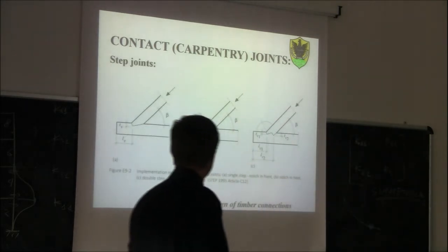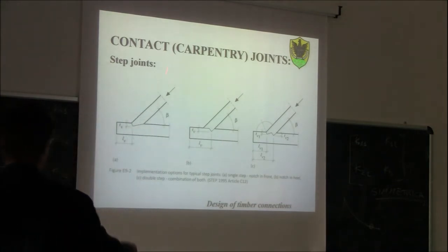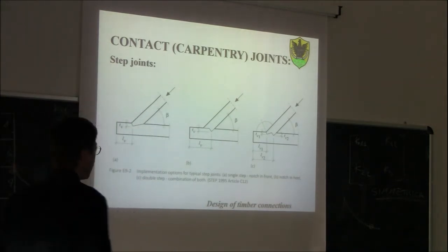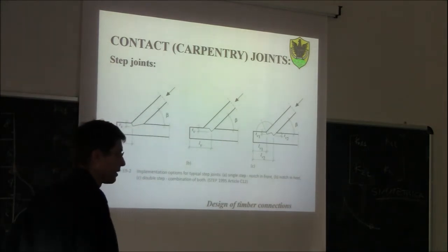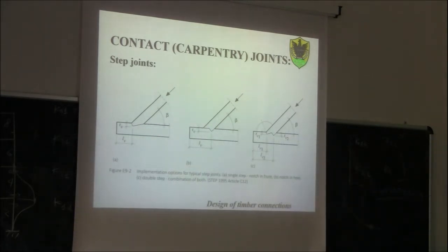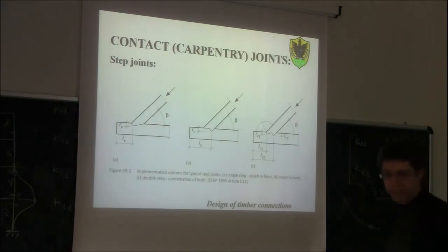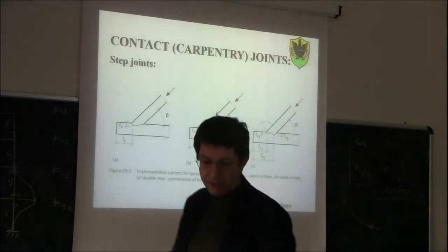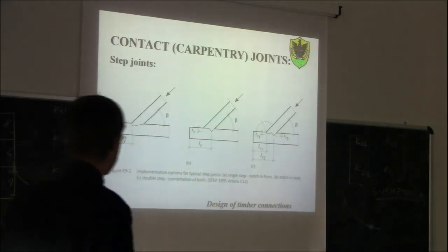So, when it comes to drawing and designing one of those connections, you just need to keep in mind that typically a truss system is designed with a pin connection. So we usually design a truss system with pin connections in order to make sure the system is statically determinate, and so we can use all the theory that we learned in the course of statics.